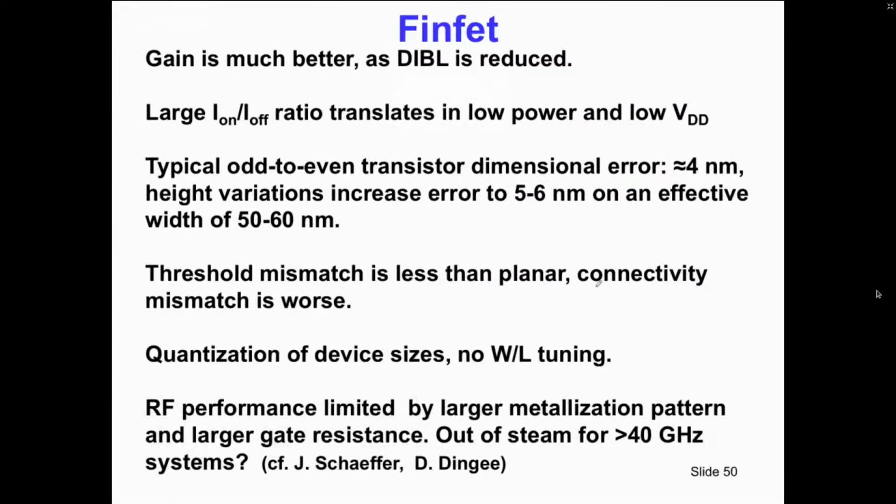In general, FinFET is better, because the drain-induced barrier lowering in a FinFET is much lower than in the standard MOS. For us, that translates into 4 or 5 times better intrinsic gain, so the gain of your output impedance and your input transconductance. You have a much better on-off ratio, and that means that you can live with a lower VDD.